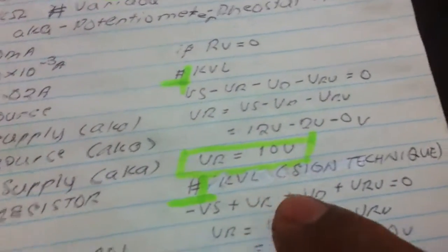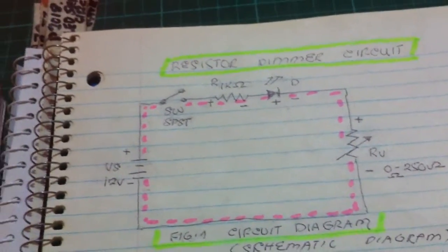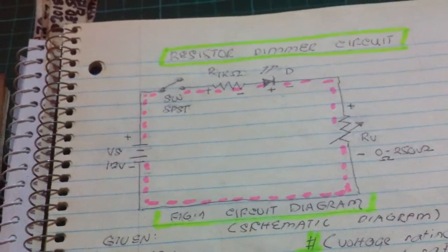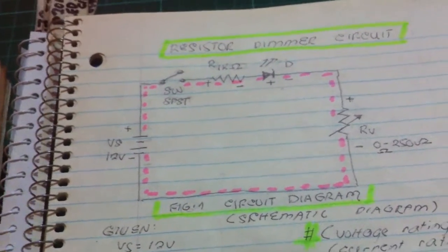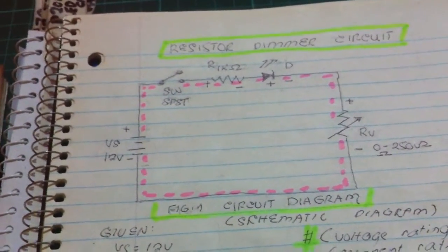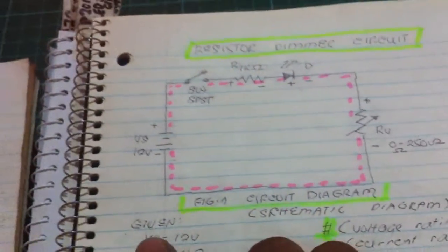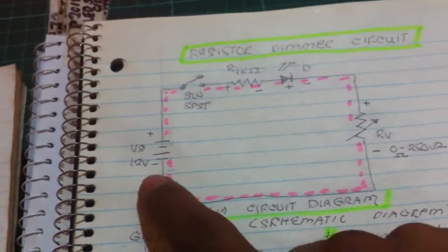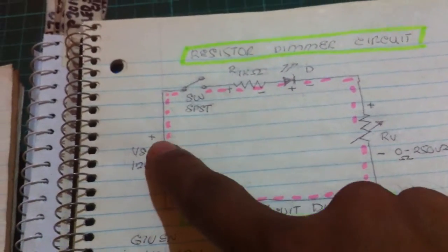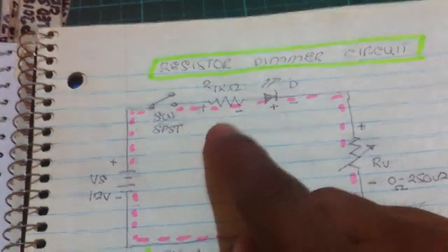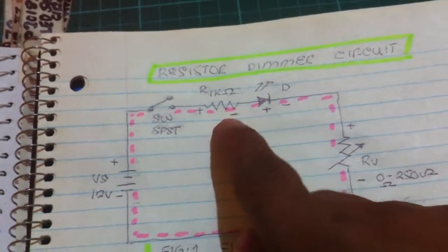So we got now here, what is this? At KVL, the sign technique. We have a sign technique here to solve this problem. Here, you are always asking where the current flows. And here's one of the techniques, the sign technique. Just follow the sign. In here, we have negative to positive voltage supply. And since the resistor is opposing the current here, it should be plus, minus.